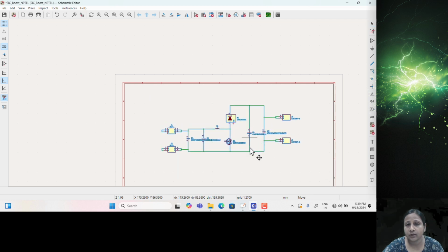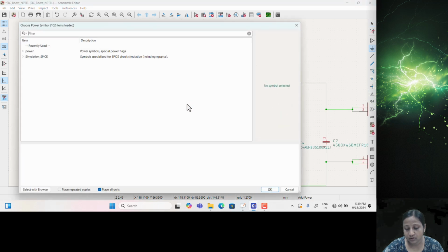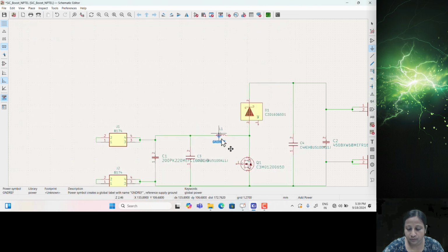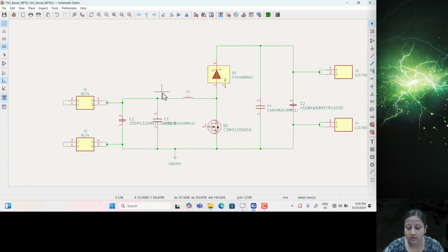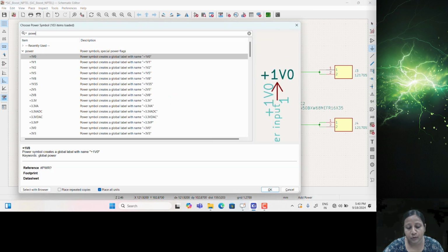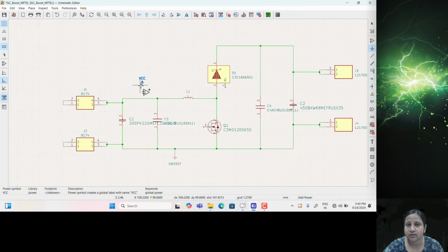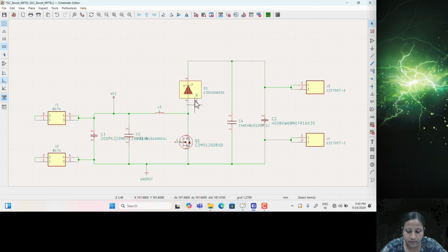So the whole system schematic is now complete. So this is the boost converter, right? One more thing here is you need to connect the ground reference. Sometimes the ground reference is the negative terminal, sometimes it may not be the negative terminal. So in that case you have to connect it separately wherever the ground connection will be. As I have discussed during the EMI discussion, the actual ground is different. So here you have to connect the positive and the ground terminal.